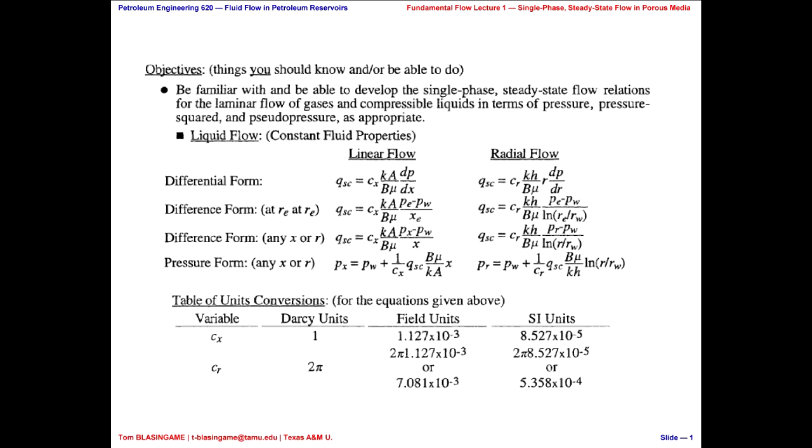So tonight we're actually going to derive the deliverability equations, but it's not going to exactly be the deliverability equation. Why? Because the deliverability equation is valid for pseudo-steady state flow. Everything we're doing tonight is steady state flow. But if you derive an equation that looks like another equation in every way, shape, or form, what's your conclusion? And don't say they're the same. Just say they happen to look alike.